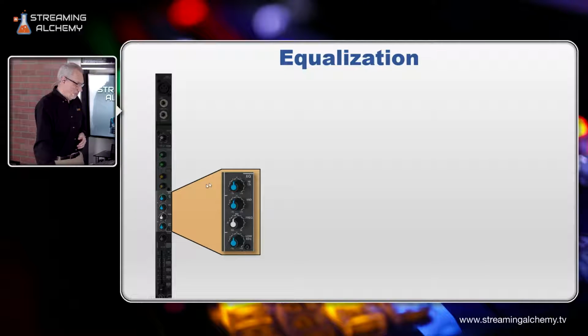But what this equalizer has that's interesting is it has something in the middle called a parametric equalizer. And in a parametric equalizer, you can actually control what that center frequency you want to adjust is. So in this case, this will let me take anything from around 200 hertz all the way up to 8,000 hertz and pick that as the center frequency and make the adjustment around that.